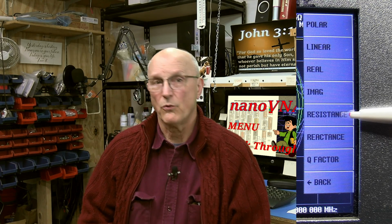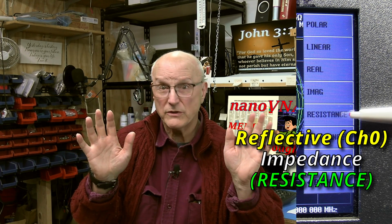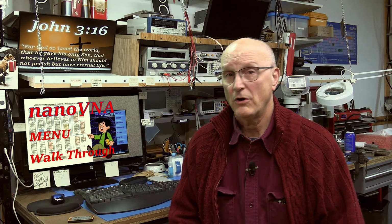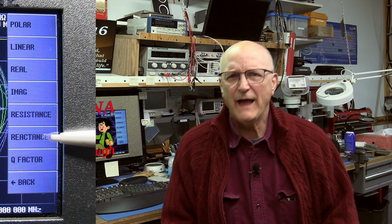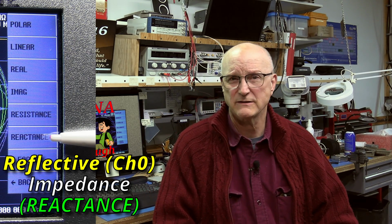Our next option relates back to the values provided in the Smith chart. It is the resistance, or real portion of the impedance. It only has meaning in the reflective mode and totally ignores the reactive portion of the impedance. There's yet one more to go. This last option also relates back to the values provided with the Smith chart. It is the reactance portion of the impedance. It too only has meaning in the reflective mode and totally ignores the resistive portion of the impedance.